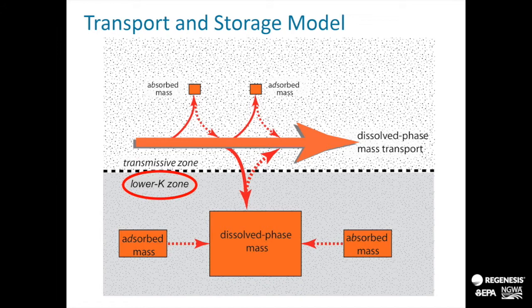So one of the other things that we did in remediation hydraulics that we'll be revising for the upcoming edition is we originally talked about the transmissive zone or the high K zone, and we originally said immobile porosity. We called it the mobile porosity and the immobile porosity, and that unfortunately tied our thinking in everybody's mind to the dual domain models. And that really was not correct. So among other things, people point out, well, porosity can't be mobile, it's not moving. So okay, I got it.